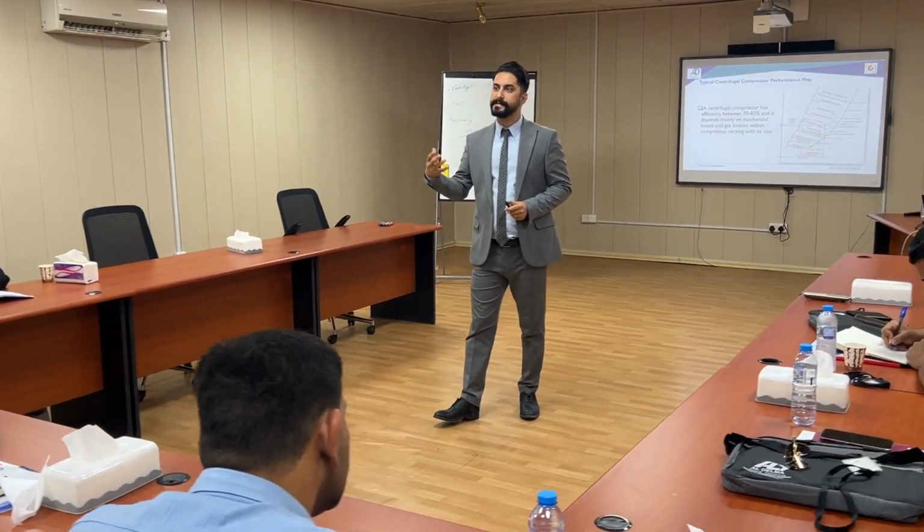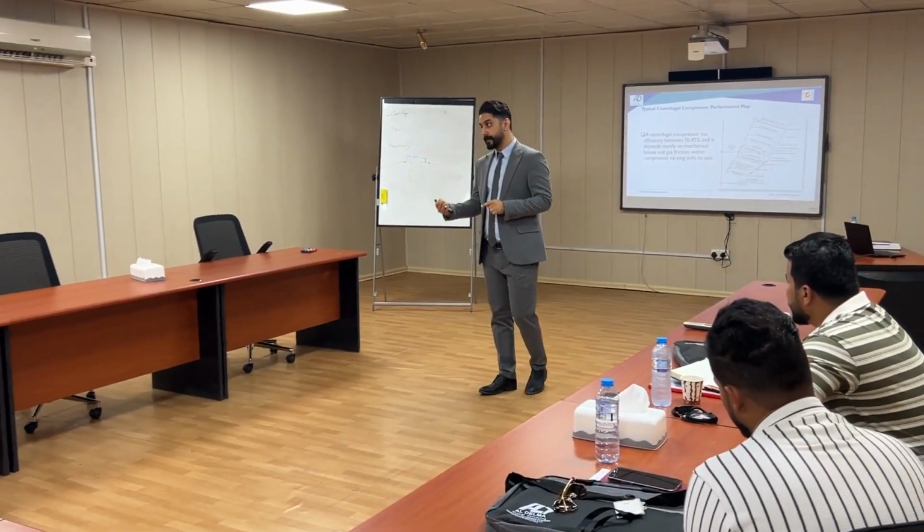Okay. What are the signs of surge? When can we say that surge is going to happen? Yeah, the main sign is the flow rate. When the flow rate is decreased, that means... very good. So we have a minimal flow rate required for the compressor to work. And also lower pressure on the suction line. The other sign is maybe high noise from the compressor. It sounds like sand. Yes, that's the vibration. Very good. So sound and vibration are the signs of surge.